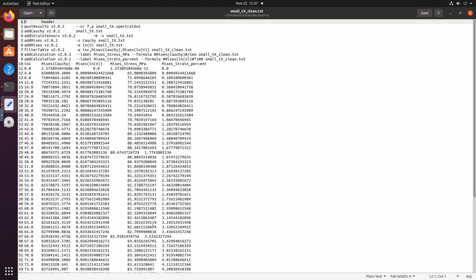If you plot this, the problem here is that these are all the averaged values, right? One of the big advantages of running crystal plasticity simulations is that we can see how the individual grains were deforming, what was the local stress state, and what was the local slip mechanism or the hardening mechanism and things like this. But these are just the average stress and strain values out of them. If we want to look at the local behavior of the material, what we want to do is we want to look at a local frame of all the elements and not the averaged values, right?